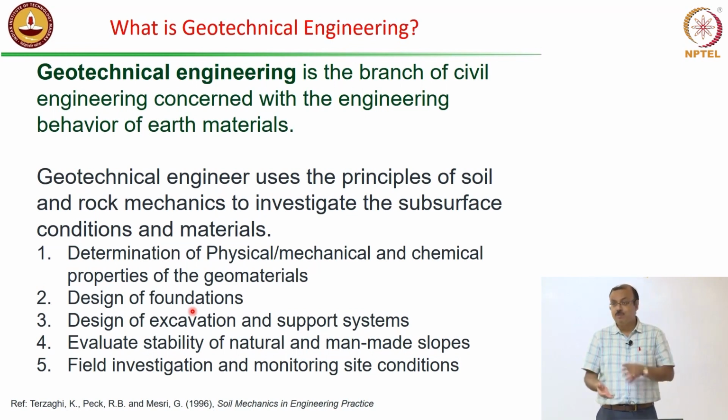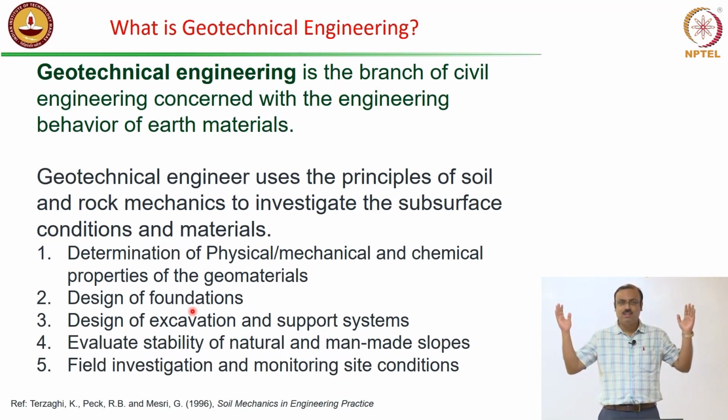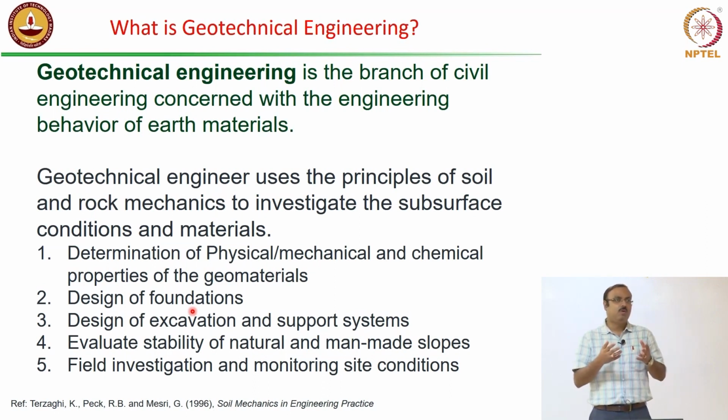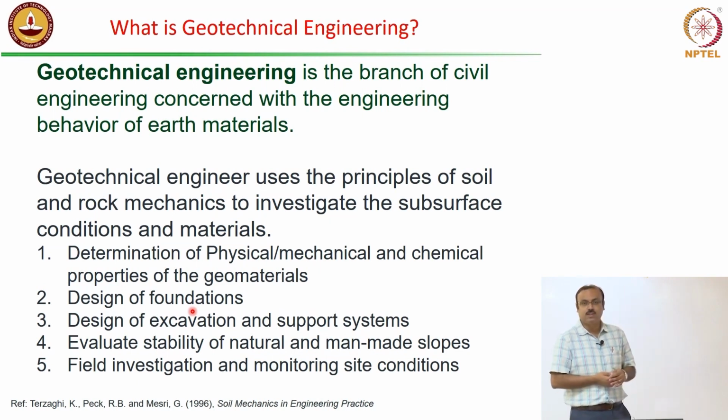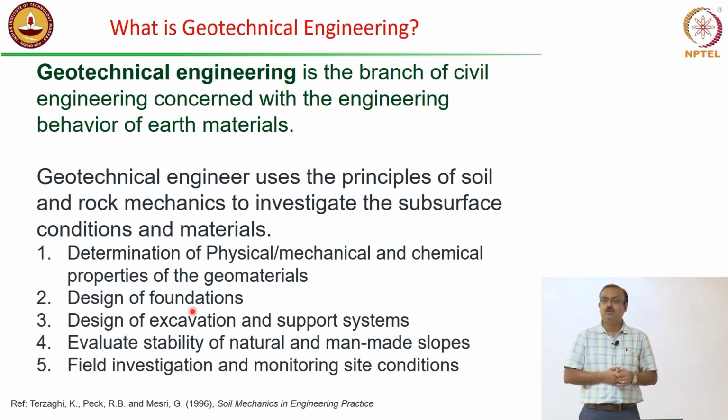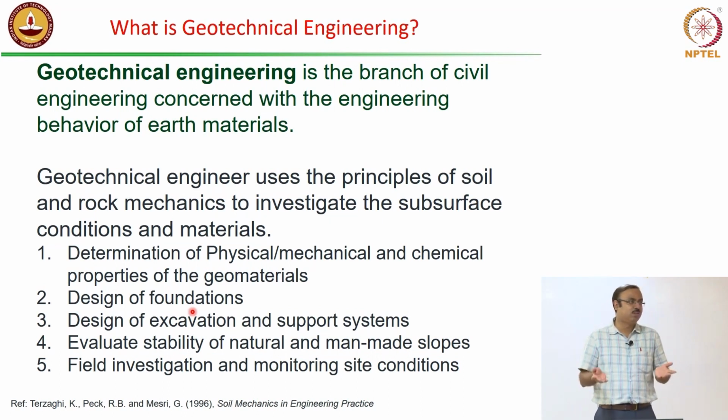You cannot simply dig up. Of course you can dig up to a certain level, beyond that the cave will collapse. So how do we support that? That's where excavation and support systems come into the picture. When you do the excavation, there should be engineering behind it. How to resist the collapsing of the soil, what depth is required, or how much depth you can safely dig without any support system. All this comes under the purview of geotechnical engineers.